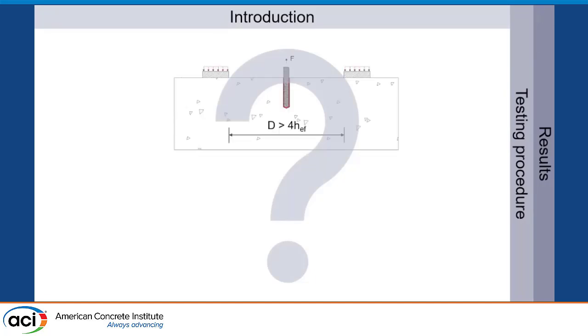Mostly there are two methods to test bonded anchors. First of all, we have the unconfined setup, as shown in this case. We have the confinement, where the support diameter is larger than 4 times the embedment depth of the anchor. Afterwards, we also have the confined test setup, where the support diameter is supposed to be 1.5 to 2 times the diameter of the drill bit. Both of these values for the support diameters are according to the current guidelines, EAD or the ACI.